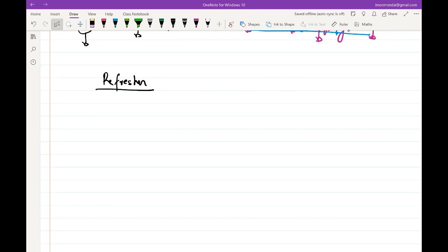So let's say I have a first order transfer function, H of S, which is 1 over 1 plus S by P. Let me call this V naught over Vi. If I tell you this is a transfer function of a real system, what can you comment on P? Is this real or imaginary? Can it be imaginary, or does it have to be only real? Mathematically, it can be either, but in a real system.